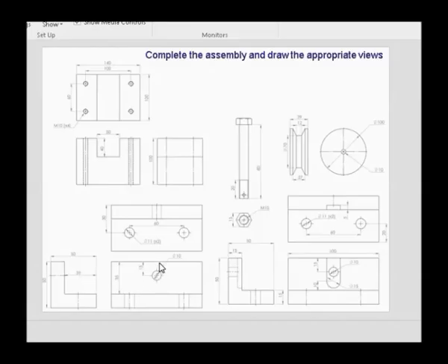There's a 10 millimeter hole drilled through it, 15 from the top. And it's got two holes in the horizontal part, 60 millimeters apart, and their diameter is 11. Okay, 60 apart, close to 10 diameter. We've seen this before somewhere. Okay, bottom right we've got another L-shaped component, but this one has a little slot cut into it. The slot has a width of 15, also has a diameter 10 hole in the middle, and the rest of the dimensions are the same as the other L-shaped component.